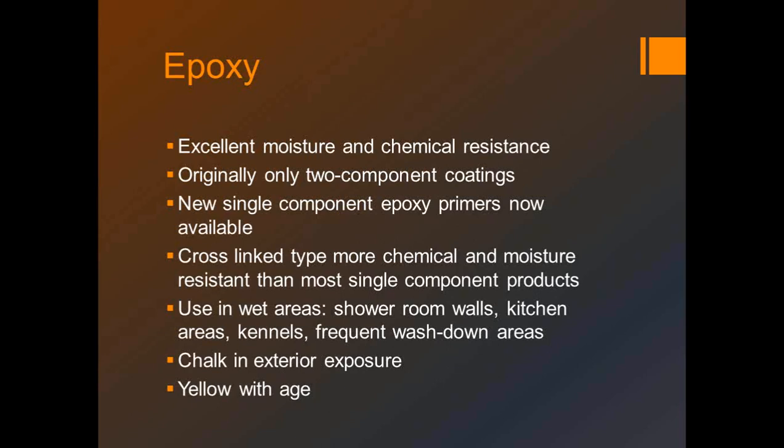We were talking about elastomerics a minute ago. Two coats of a waterproofing polyamide or wall-proofing epoxy ester block filler and a coat of elastomeric can do a great job of waterproofing a CMU wall. Some years ago, I did a juvenile detention facility, and we actually specified 2 coats of block filler, because we wanted to absolutely minimize the surface indentations, the variations that could hold dirt and grease and grime and so forth, and it turned out really very nice.